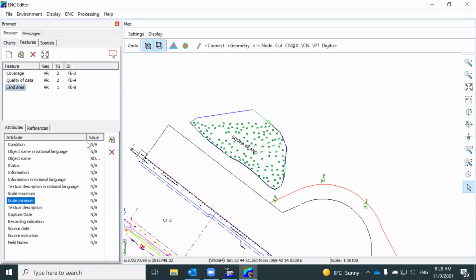If you see a question mark, it's a mandatory attribute, so you have to set it up in any case. If you don't see the question mark in the attribute properties here, it means that it's not required. Of course, it's better to have, let's say, the name of the object, right? You want to see the Boca Island label on your island, so why not?